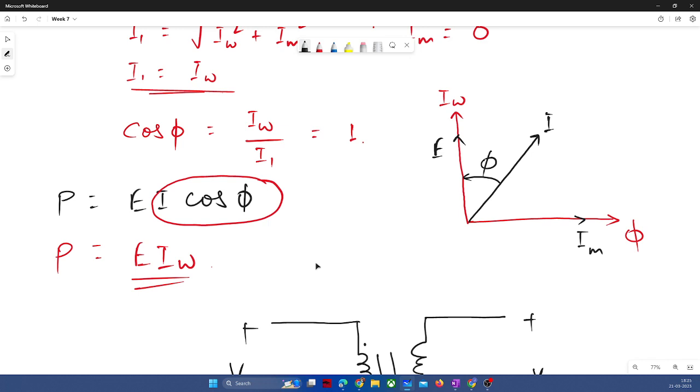So this P is the actual active power transferred from primary to secondary side? So is the active power transferred nothing but the power lost in hysteresis and eddy current? Yeah, if no load is there, if it is an open connection, then whatever active power is there will be your no load losses. It means iron loss, and iron loss has two components: eddy current losses and hysteresis losses.